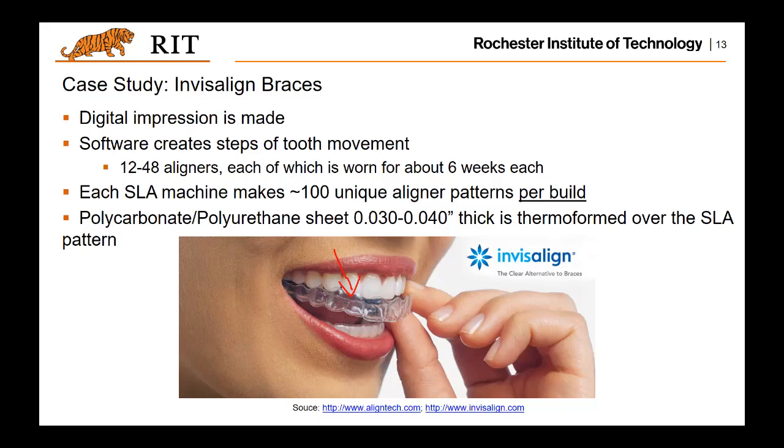Basically, they utilize the 3D printed teeth as a die and utilize this polycarbonate sheet material, and then a forming process happens, and it turns out that will be your final liner produced. So they skip this forming die punching process, but I just want you to have a correct concept of how they actually do it.